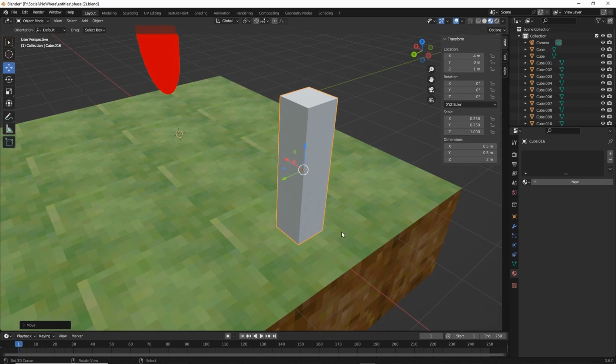Right, so material. We can either click the plus button, because this is a new mesh primitive, just a cube. It has no material assigned to it by default. That only is assigned for the starter cube. Anything we add after the fact does not carry a material normally. So we can either click the plus or the new button. Plus will add an instance that's not populated, so this will be blank, or we can just click new and it'll create an instance and populate it.